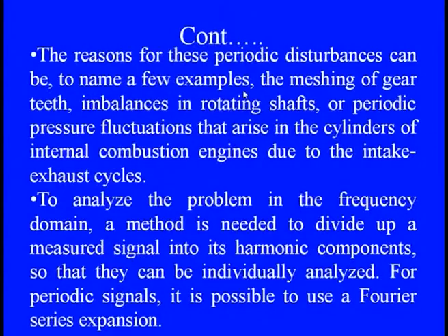To analyze these problems in the frequency domain, a method is required by which the measured signal is divided into harmonic components, which can be individually analyzed and then linearly summed up. So, for a periodic signal it is quite possible to use the Fourier series expansion, and then we can pick out the exciting frequencies.